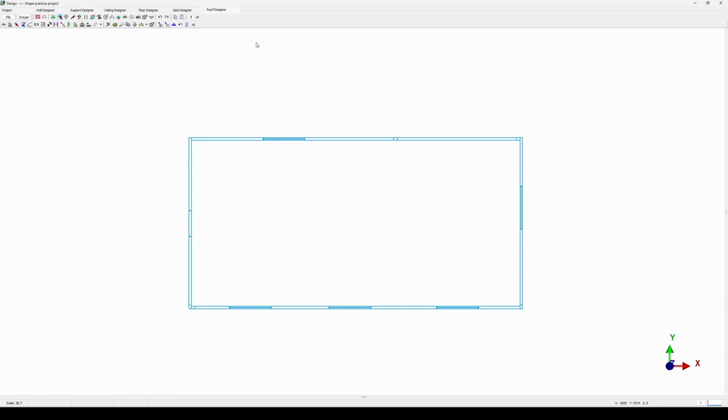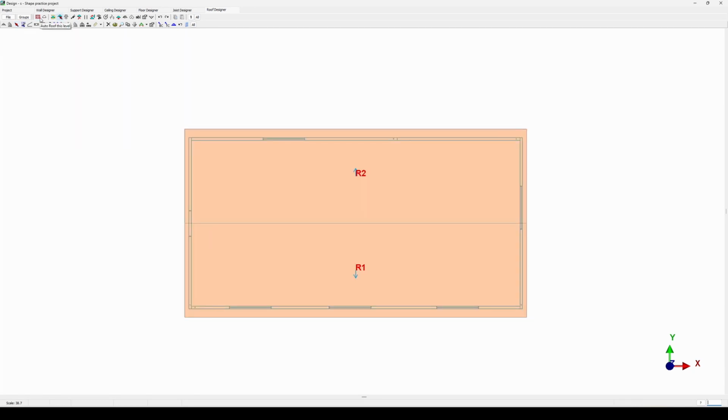To get started, we're just inserting a roof plane by using the auto roof function. To insert a truss, you'll be using some tools to select your profiles to generate a shape for the roof truss. Without those profiles selected, you don't have a shape to connect your trusses to. So within the Truss Designer tab in the bottom row of tools, we're going to go to the far right hand side. We've got these two buttons called BC and TC. The BC is short for the bottom chord selection, and the TC is short for top chord selection.